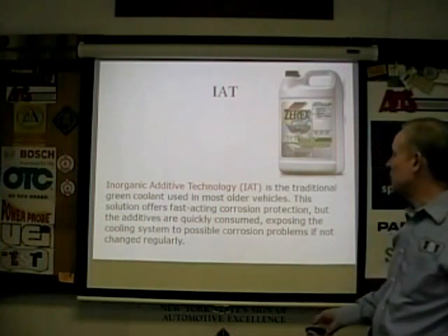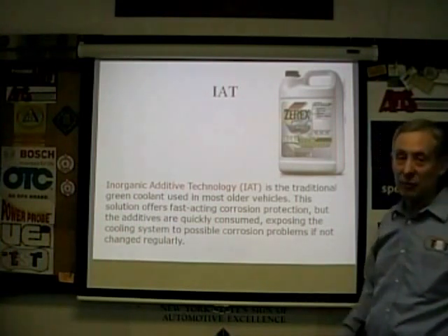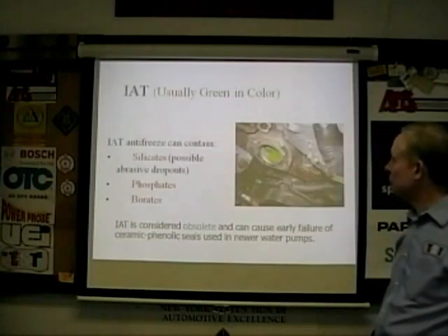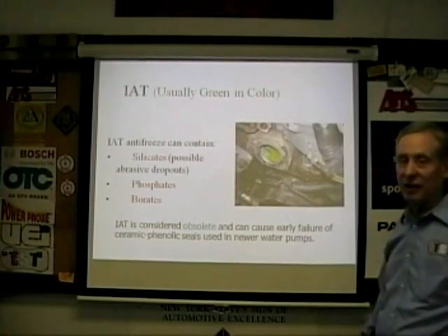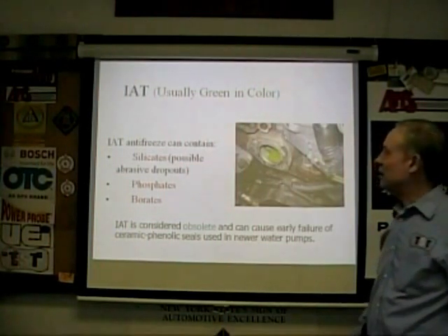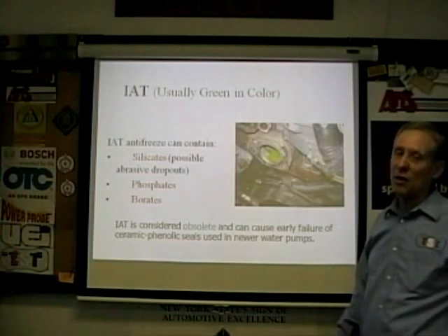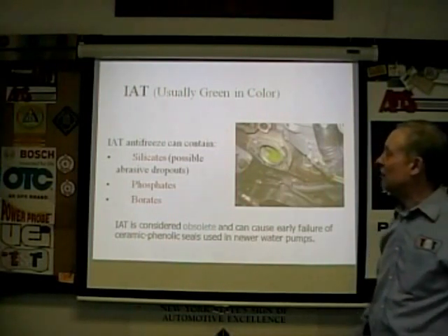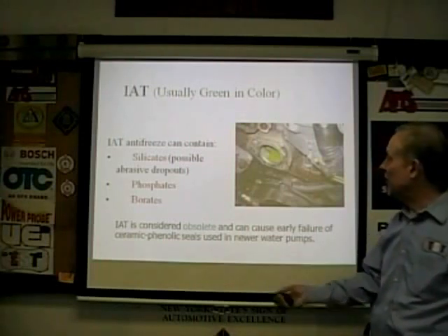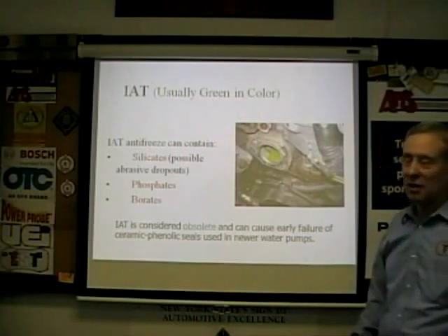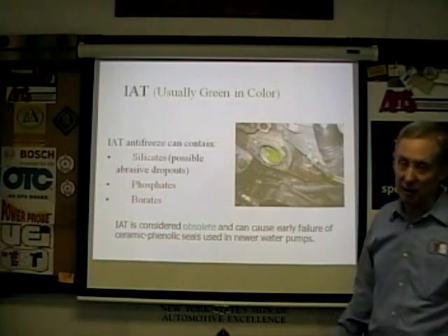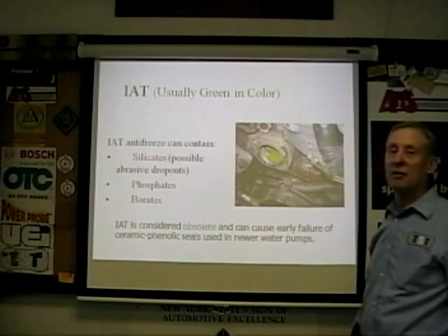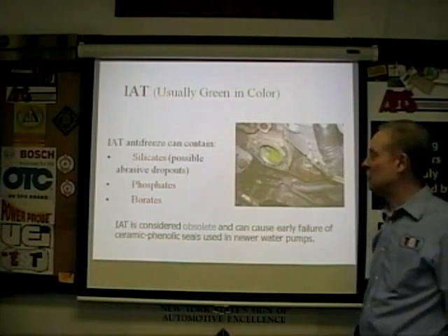All right, this is the traditional stuff. You have to change it regularly, and it's become pretty much obsolete, actually. It's usually green. That's the green coolant we're used to. It can contain silicates, which is one of the reasons they've gotten rid of this stuff. They're abrasive dropouts. They cause all kinds of trouble. Phosphates and borates. Not only do they offer problems in the cooling system, but they're oftentimes incompatible with modern catalytic converters, modern pollution control equipment, let's call it.